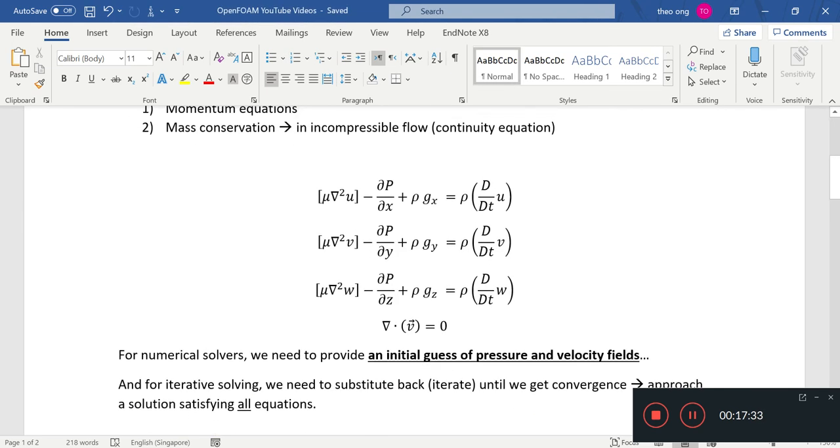So what we have basically done is guess the pressure, set an initial pressure field, and then get a velocity field from this by solving these three simultaneously, and the OpenFOAM solver or whatever numerical solver will do it for us. Then we substitute all of this into the continuity equation. Unfortunately, the only feedback that this continuity equation gives us is a yes or no answer.